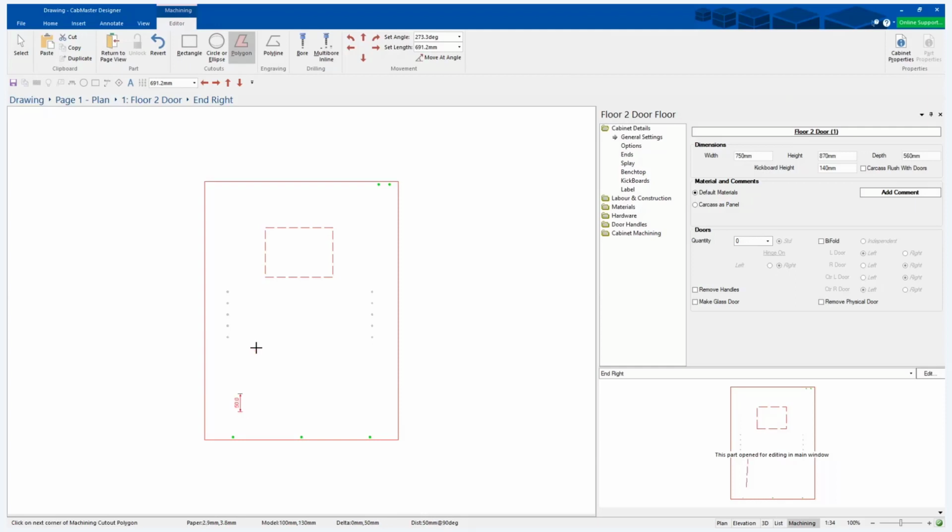You start dragging the line, and you hit the numbers on your keyboard, 1 to 9, and it'll give you the length that you specified as your quick length. So then you start dragging it, hit the number, and that's going 60 by 60 across, because number 6 is 60.